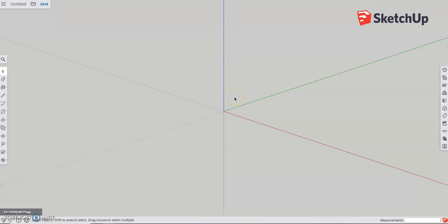Once you're here, what we want to do is set up a 2D object, and then we can transform that into a 3D object, and then we can copy and paste to get what we want. I'm going to start on the left over here. I'm going to select the icon called Rectangle. It'll open up several different options, but I just want the first one, which is called Rectangle. This should give you a red pencil with a blue rectangle on it. That tells me that I'm drawing along my top axis, along the right side and the front.